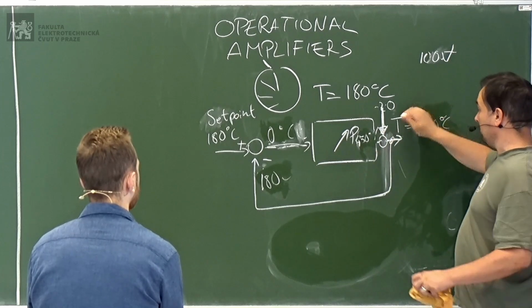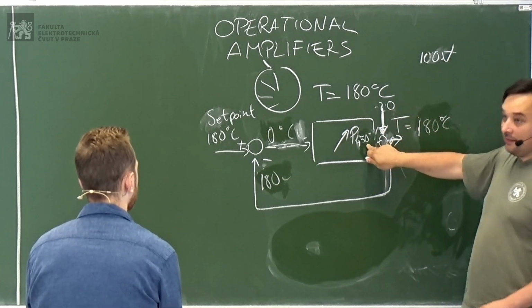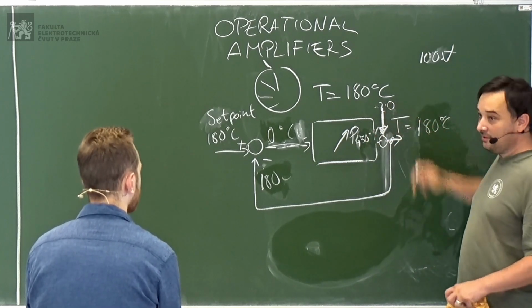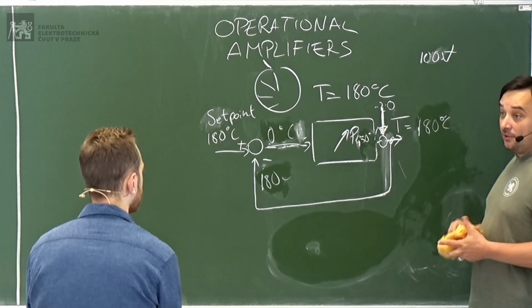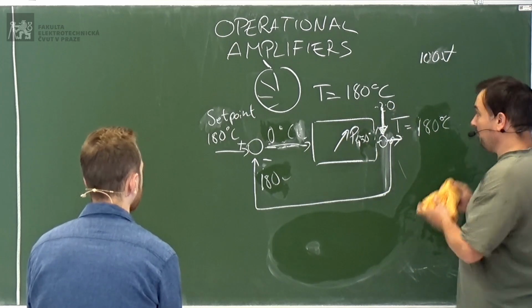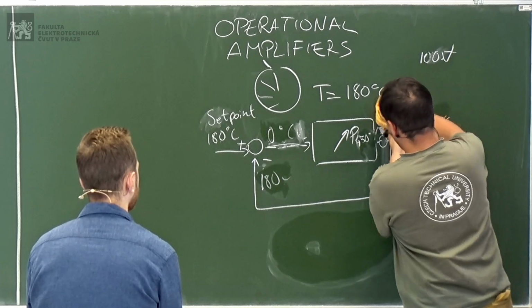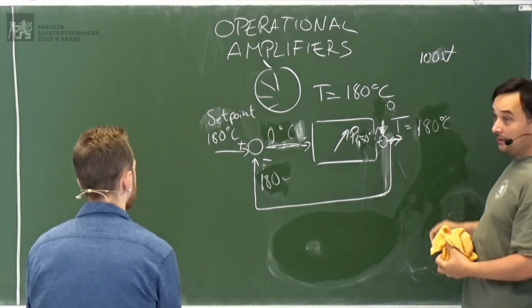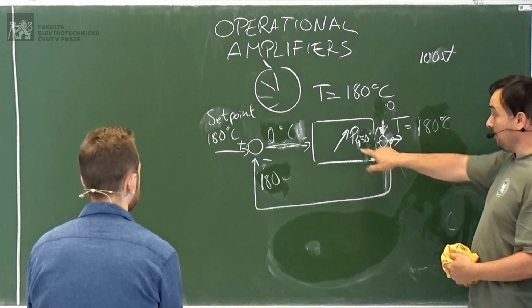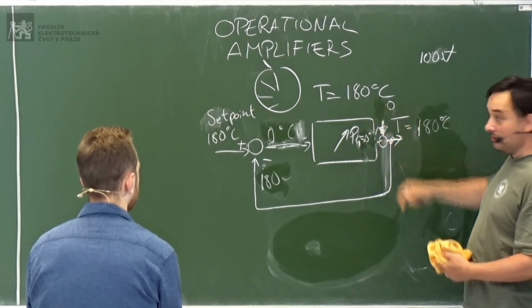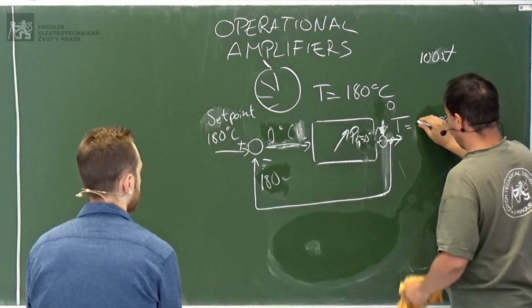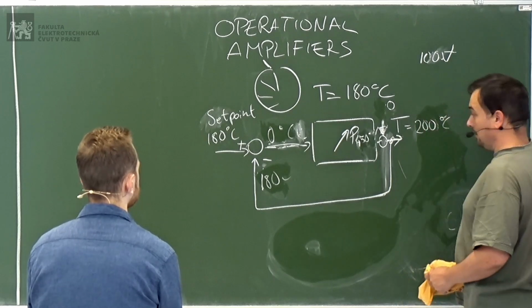And then, fine, now I have 450 watts, it's enough with this disturbance. I remove the disturbance, for instance, I close the door of the oven, now this becomes 0. Now this will become larger because I have more power but no disturbance. So it will be 200 degrees.